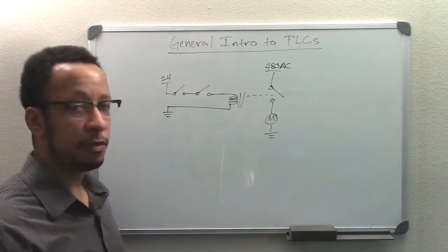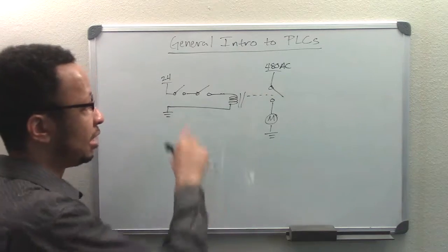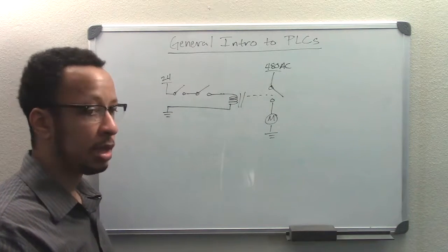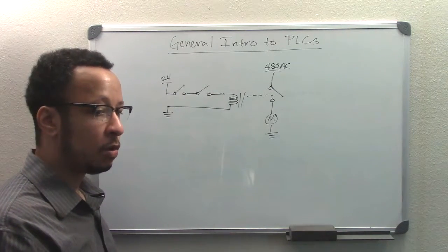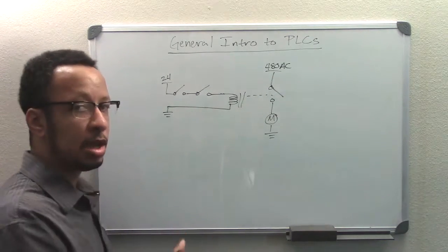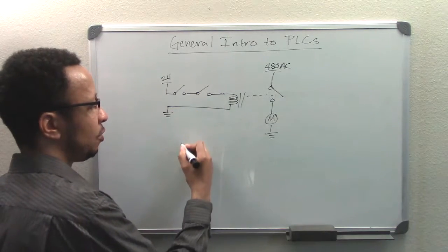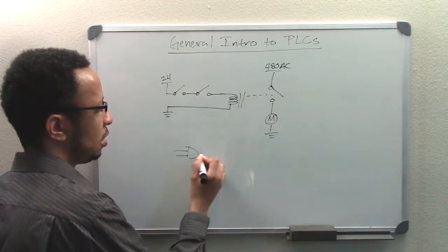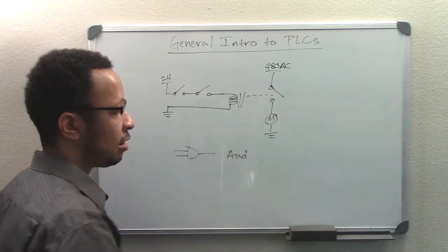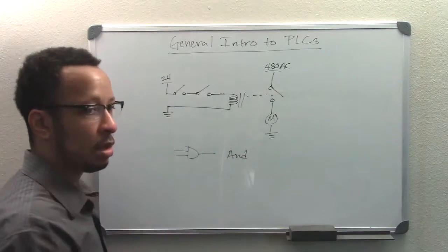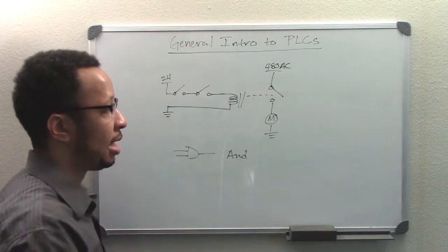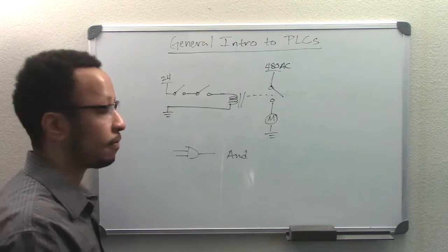But if I closed both of them, then what would happen? Well, we'd have electric current through here, and then now we would have an electromagnet. And so in doing that, what we can automatically pick up on here is that this is an AND situation. Remember our digital gate that we had before, our digital function for AND? What it requires for an output is that both of these inputs are high, those conditions are met, and then we have that AND function.